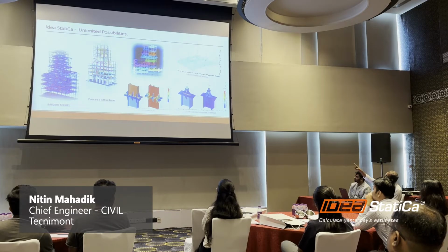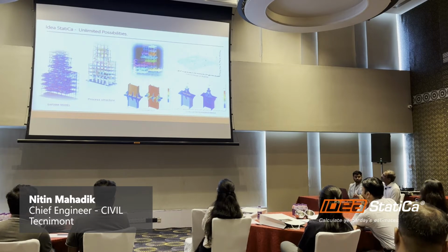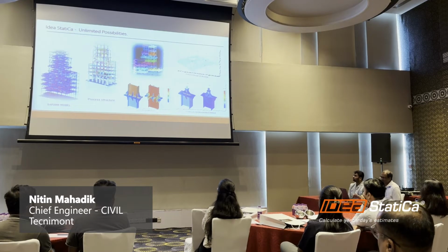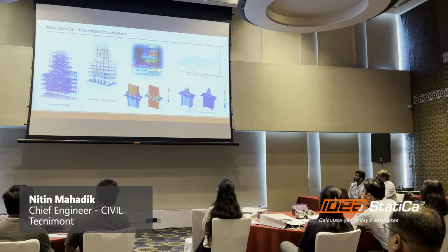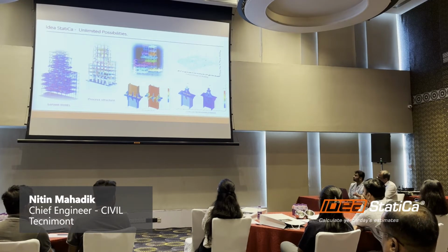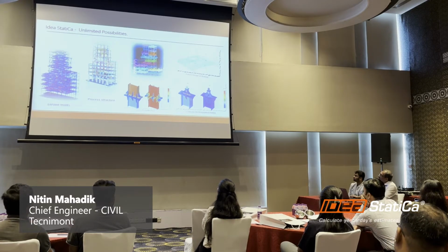And here are the lifting lugs. You can see the lifting lugs. We analyzed them in IDEA StatiCa. These lifting lugs are such that they can be reused many times. The splices and the bolt spacing are so customized that we need not use a different lifting lug at each module. So this is how we conceptualize the entire structure in order to get the maximum benefits of IDEA StatiCa and this modular structure, I mean modeling philosophy, which we implemented in this entire life cycle.